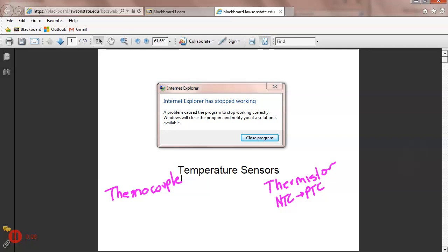So a thermistor changes its resistance. So if I need a voltage out of a thermistor, I'm going to have to use it either in a Wheatstone bridge, right? You understand? The Wheatstone bridge allows me to set a zero reference, or I'm going to have to use it in series with a resistor, right? Everybody understand, with a fixed resistor. But there the reference doesn't really mean anything.